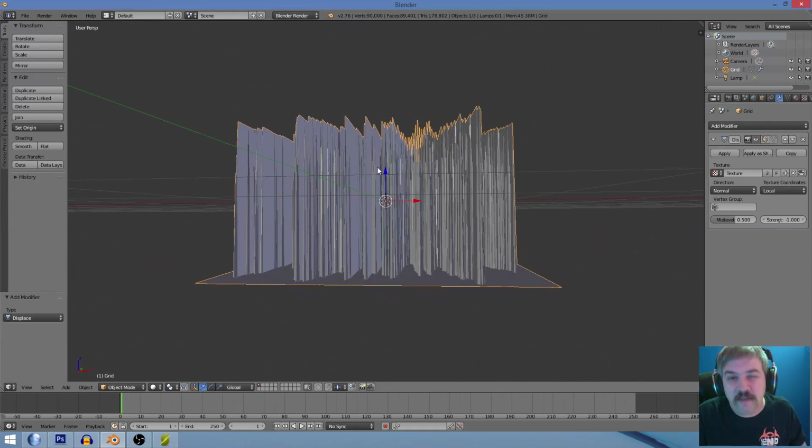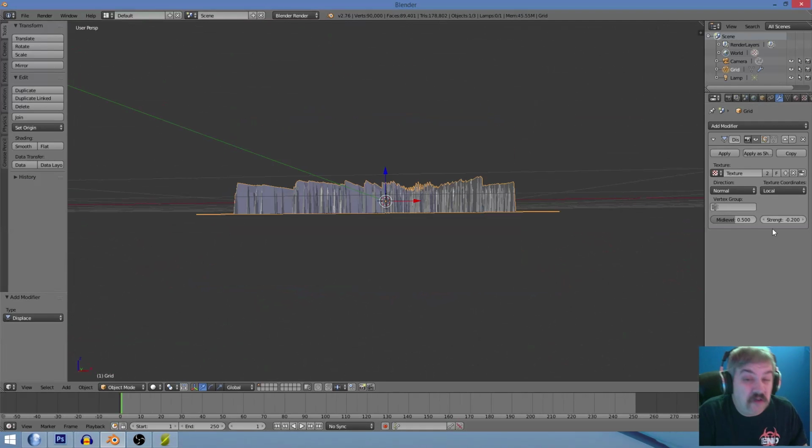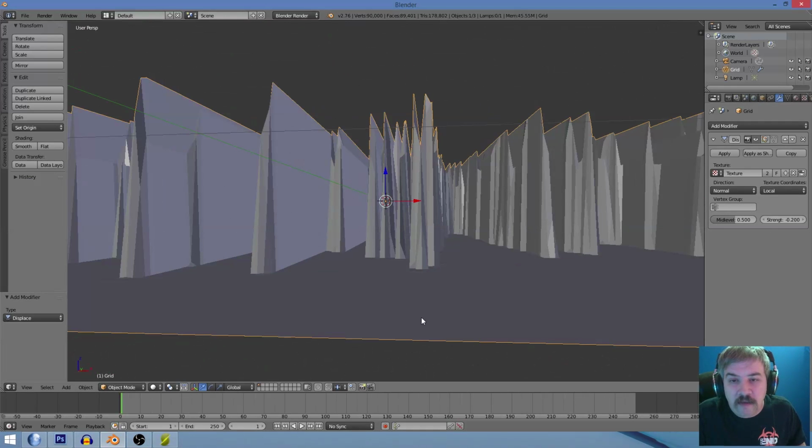Do you see where this break is, where the grays are? It's really high on the model, and we'll fix that in the slicer if you don't like how that is. You could go back and lighten your grays in your photo editing program, but we can fix that in the slicing program. This is so high, I'm just going to change this to -0.2 maybe. Oh, that's much better. I like that.